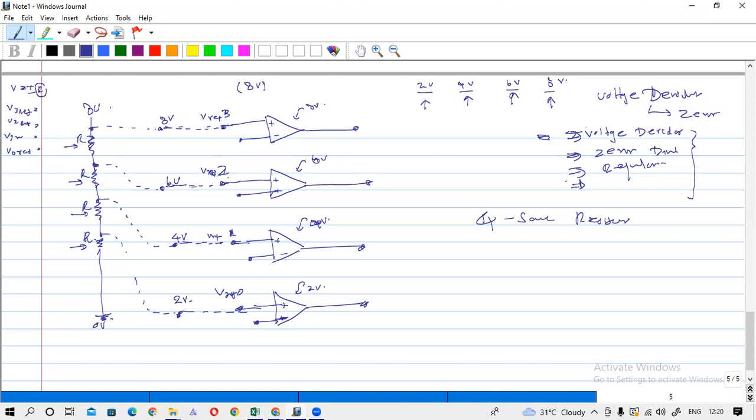So you can use V equals IR again. In this case R is for a single R, and in other cases R will be the sum, but the same I, because this is a serially connected resistor. So I is the same. You can use Ohm's law and find the voltage value here. If you can't remember this voltage divider, work it out with me.